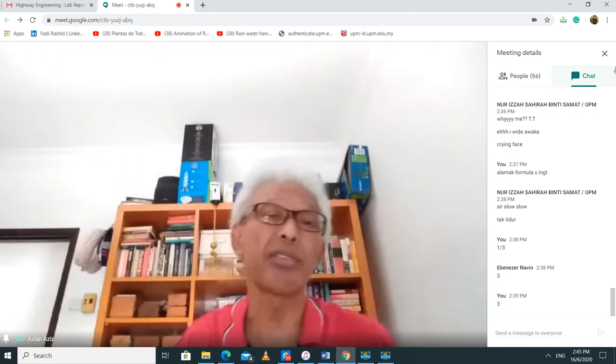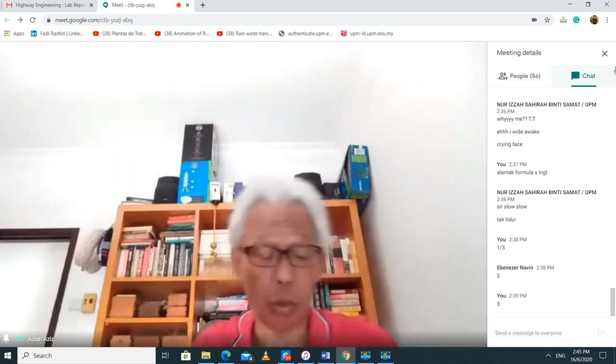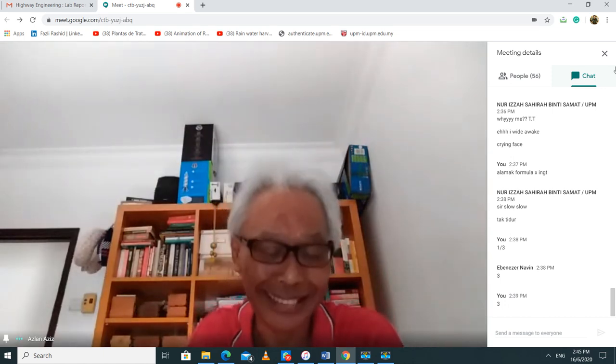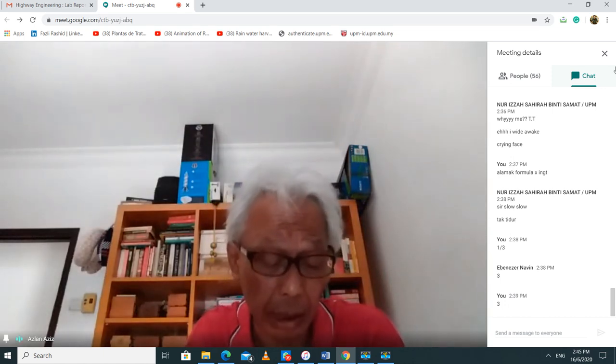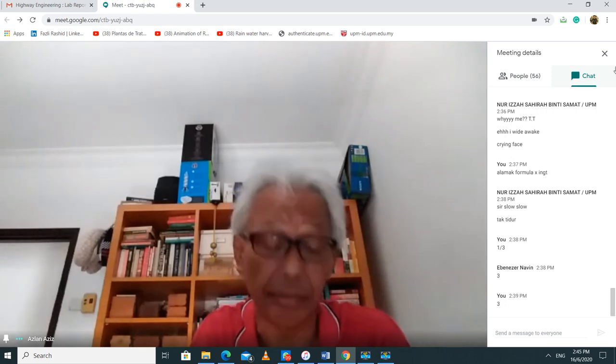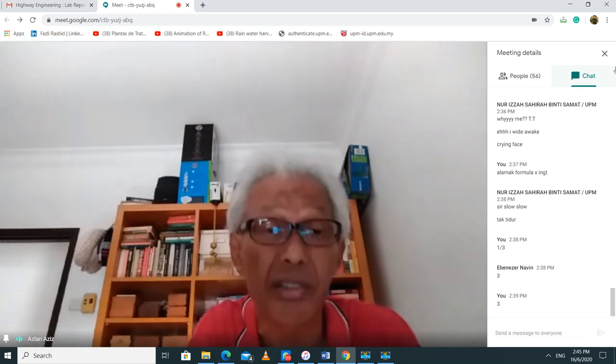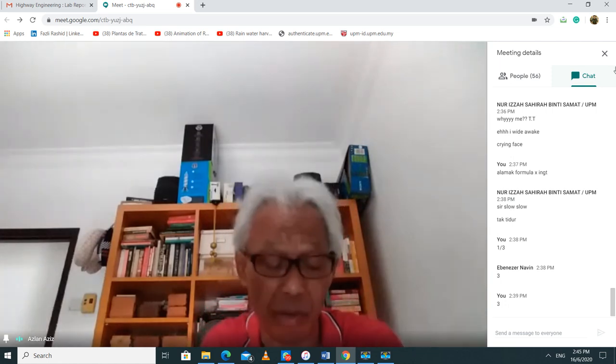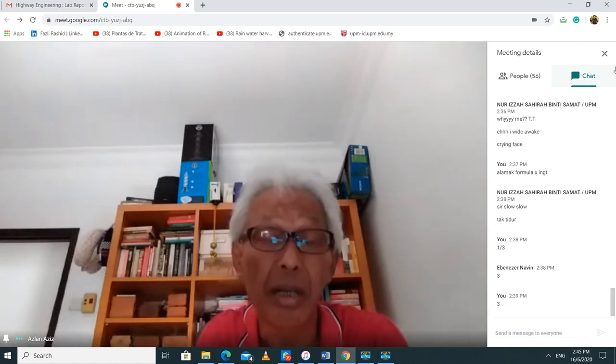Sometimes you refer to this as normal stress. I have sigma 1, and this is reflected in the active case. Sigma 1 is the vertical stress, so it is the major principal stress, and sigma 3 is the horizontal stress.